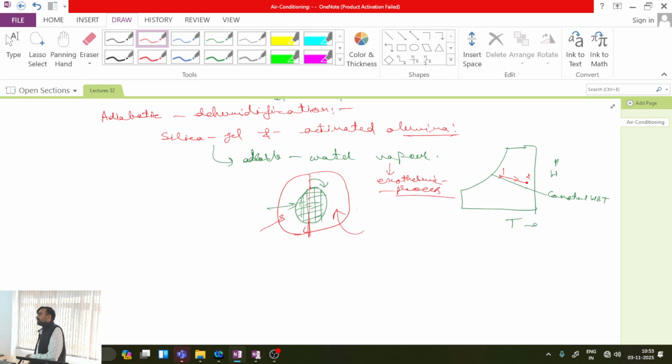Whenever we mix ethylene glycol, etc., the freezing point decreases, so we can use the air washer even for low temperature application. Other than that, even above 0 degrees Celsius we sometimes add these. The reason is that the addition of ethylene glycol, etc., decreases the water vapor pressure at a given temperature.